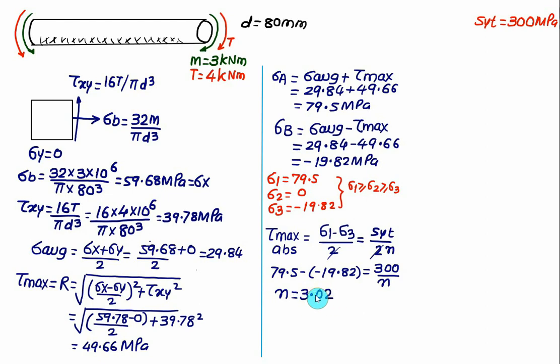Now this procedure is a time-consuming technique as far as GATE is concerned. I will give you one shortcut method. In torsion, we have developed the concept of equivalent torque and equivalent bending moment if the shaft is subjected to pure bending and torsion.